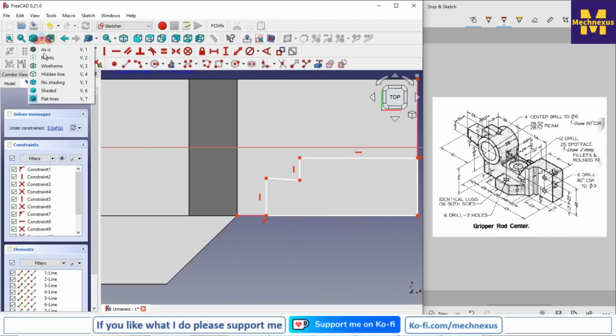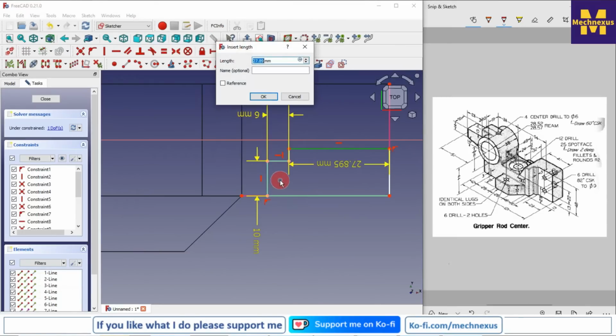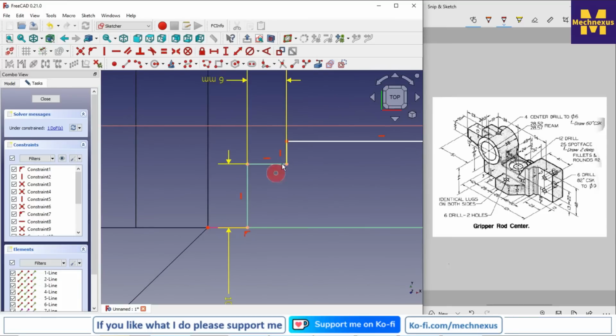We will switch to the wireframe. Now we will add a horizontal relation, and now we will give the dimensions. So this will be the 10 mm. This will be the 6 mm. This will be the 29. And this will be the 3 mm.